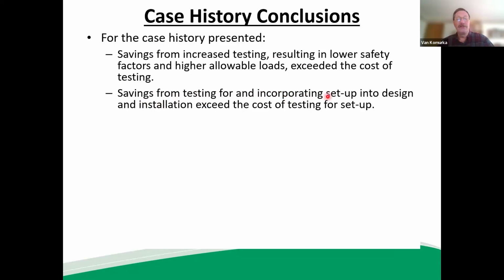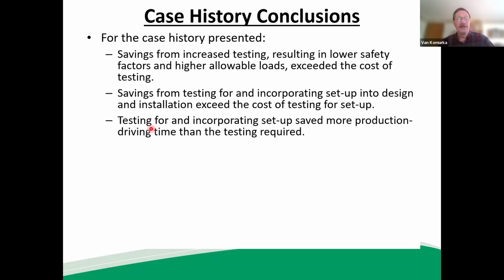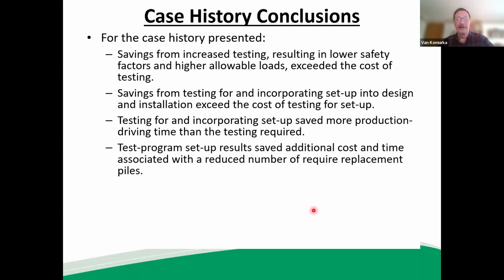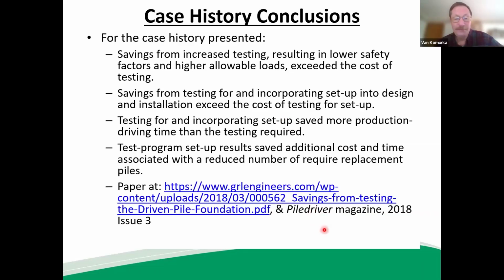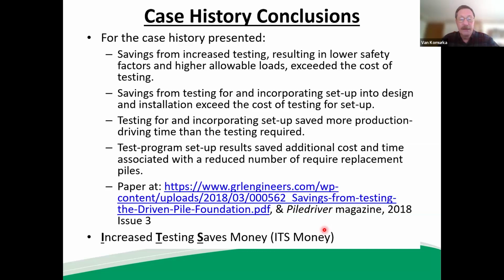The savings for setup alone more than paid for the cost of testing for setup. The time in drive time saved more than made up for the time it took to test for the setup. And again, here's a link to the paper, or at least again on GRL's website. There's a paper there. It's actually 2 papers there talking about this case history, and there's an article of a little bit lighter read in Pile Driving Magazine. So shout out to DFI and their Increased Testing Saves Money webinar series. This is a great case history to illustrate that.